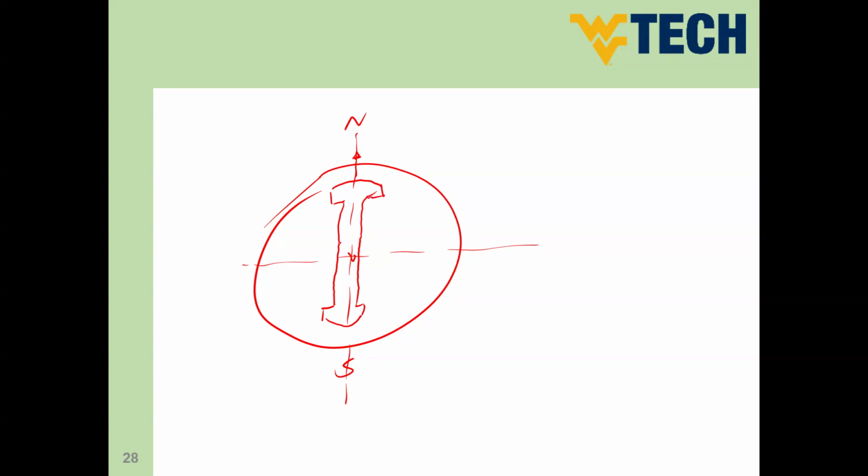So let's say this is the direct axis of our motor. Later on, you will understand what the direct axis and the quadrature axis mean. But this is the main axis of our rotor right now. If the rotor axis is in the same direction as the flux, this means the power angle equals 0. So in this case, we do not deliver any power from this machine.